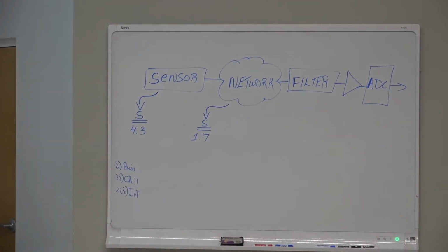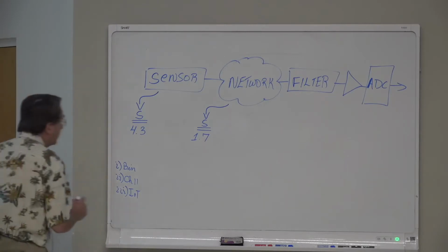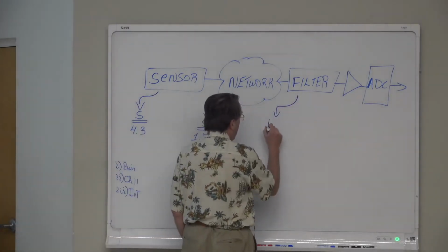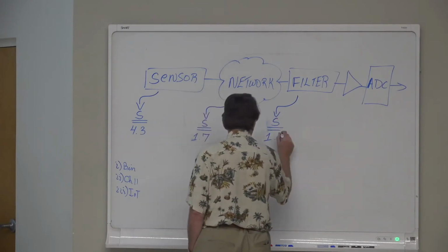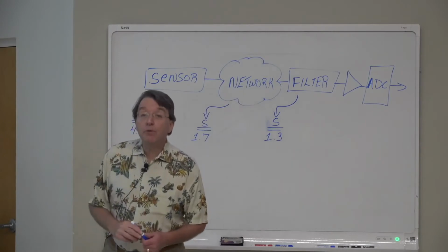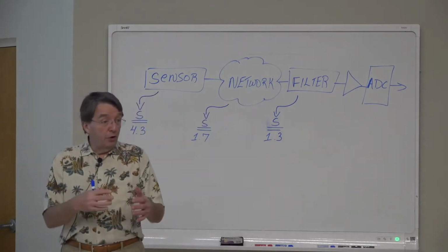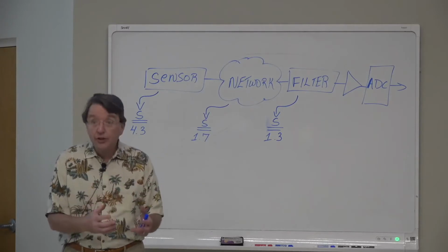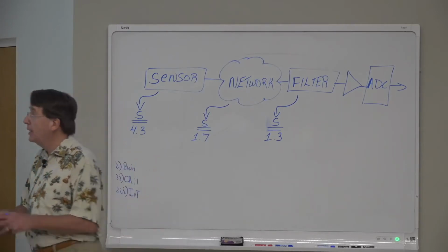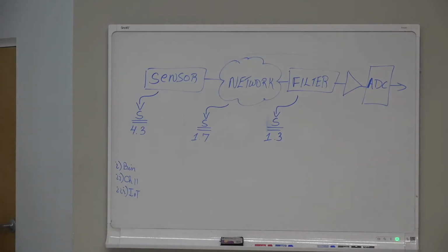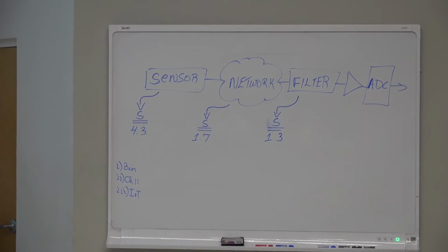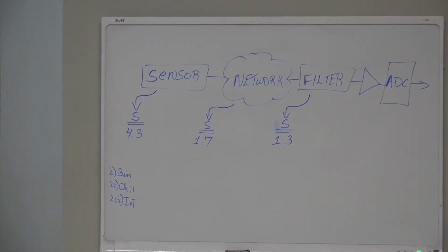I then go on to say the A to D converter, let me read the filter, sorry. In a separate test of the filter, a large number of tests resulted in a standard deviation of 1.3. Now, I remember, my colleagues, in Chapter 7, when we were discussing this, when we say a large number of tests were done, that means it was done before the system was put together. So someone tested the sensor in the lab, someone tested the wireless network and the filter. And so I got the filter. Now it says the A to D converter may produce a random uncertainty of 2.5.